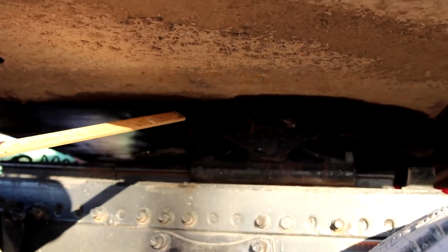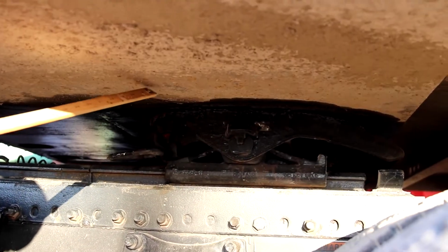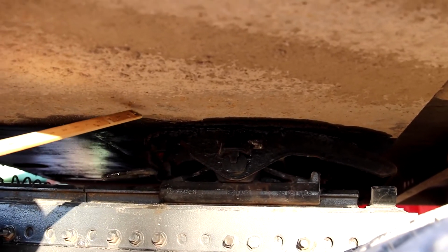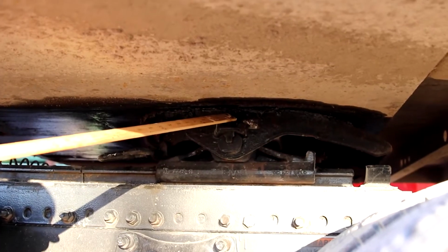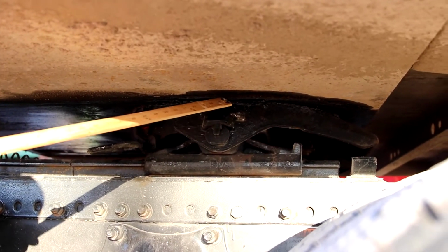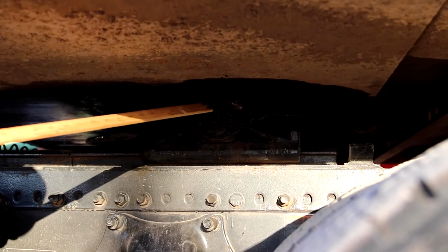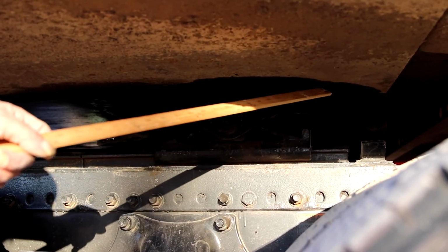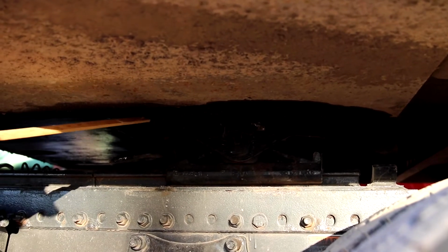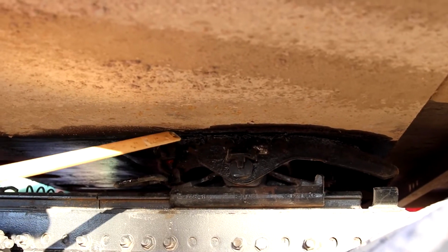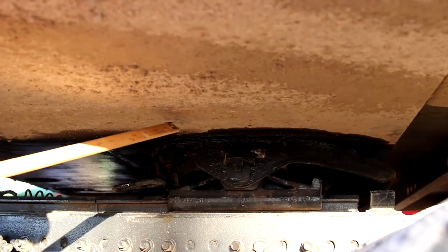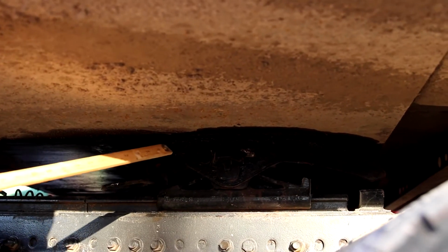Our apron, we've already talked about that earlier, is mounted securely to the trailer. It's not damaged or broken, and it's held in place with factory welds. Between the skid plate and the apron, there should be no daylight between the skid plate and the apron. If you have daylight in there, one, your coupling is probably not good. Recheck it before you move the truck, or two, you might not be on level ground.